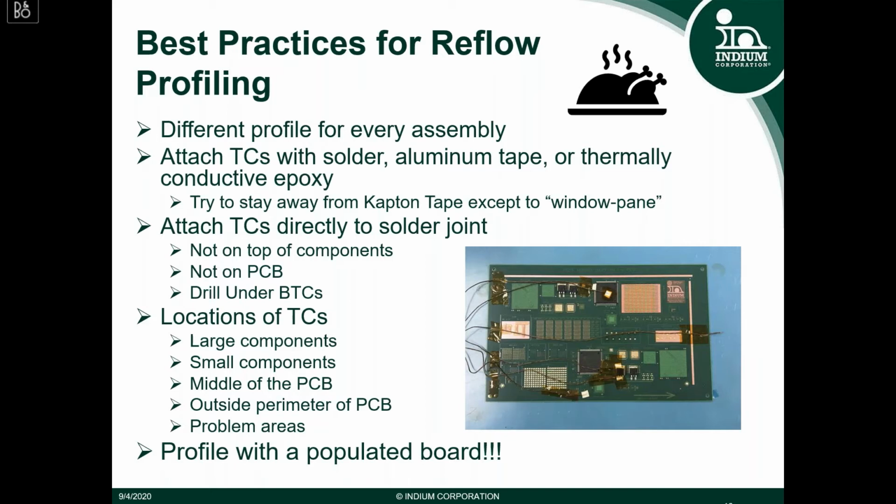I'll also use Kapton tape to window pane around the aluminum tape if I'm using aluminum tape. The aluminum tape could pop up after multiple reflow cycles, so Kapton tape secures the aluminum tape down a little more so that it doesn't pop up during the reflow step. Be careful that the Kapton tape does not cover the tip of the thermocouple where the reading is being measured. It's important to attach the thermocouples directly to the solder joint.